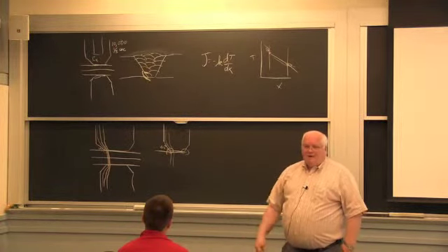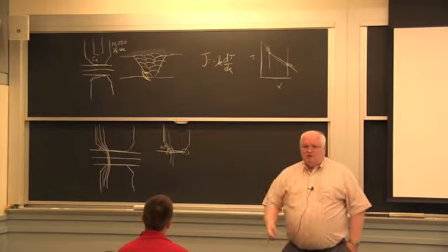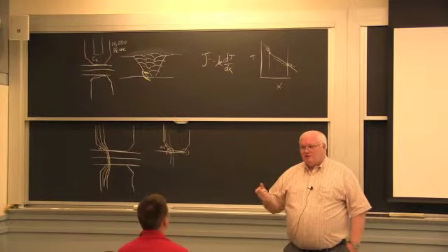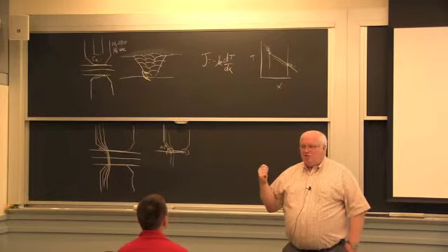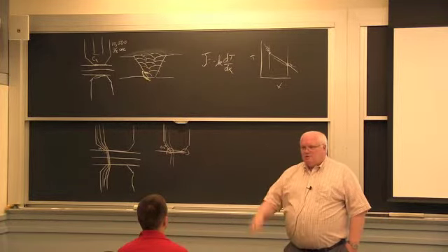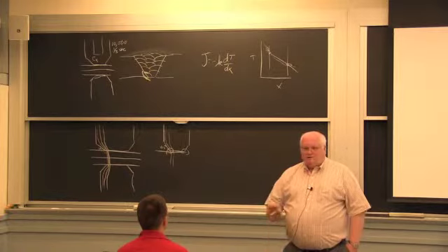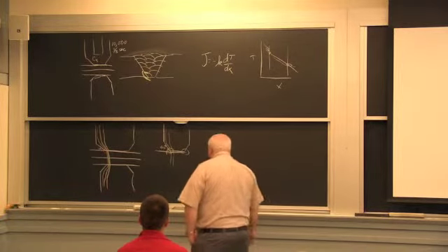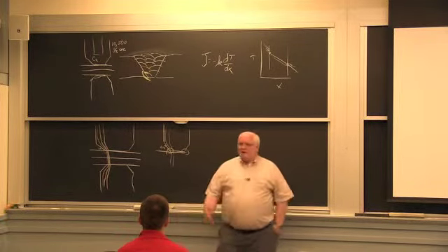Okay? The mathematics of this is the same thing as a mechanical stress concentration. This is just an electrical current concentration. But it's all Laplace's equation. Okay? So it all comes out of Ragnar Holm and electrical contacts. Okay?